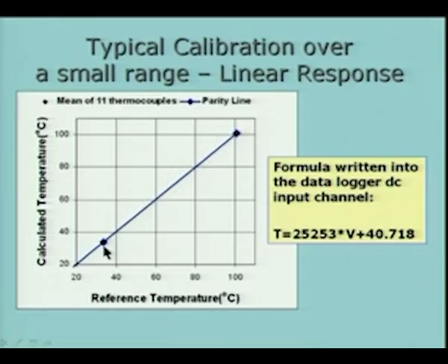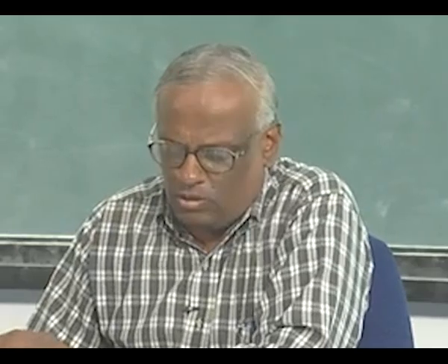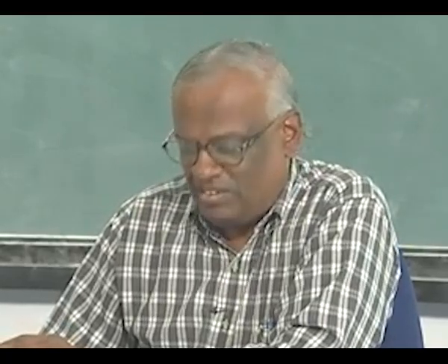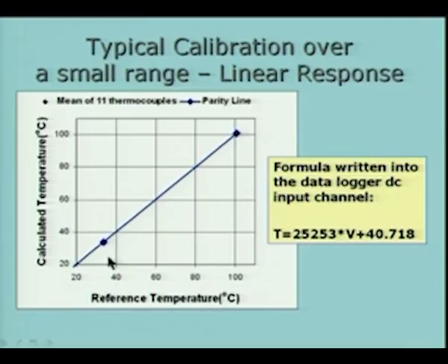In fact, all thermocouples do not follow the exact values given here. So, they have some variations amongst them, and on the average, there is an equality between the calibrated or the calculated value and the reference temperature. That means this figure is really giving you only part of the answer. The correct answer is here. So, what I am going to measure is this value V. This V is going to be measured by the data logger or gathered by the data logger.